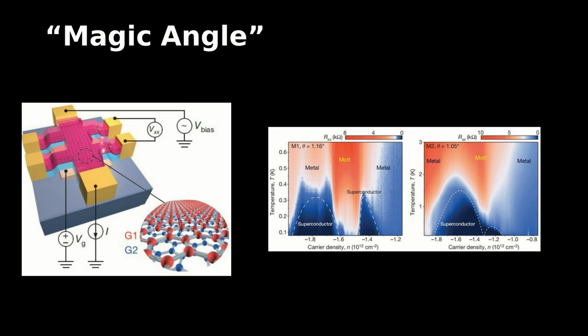The left graph here shows a device for bilayer graphene study. The purple and blue layers are the testing material. A bias potential is applied between the two layers to distinguish them in the potential field. The charge carrier density N is controlled via the metal gate below the testing material.